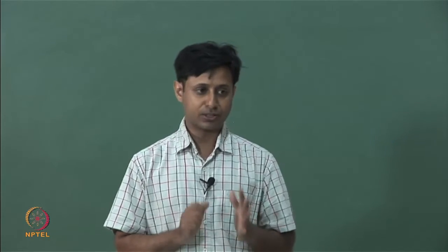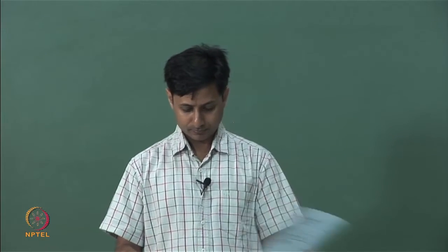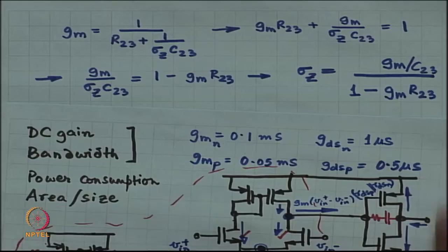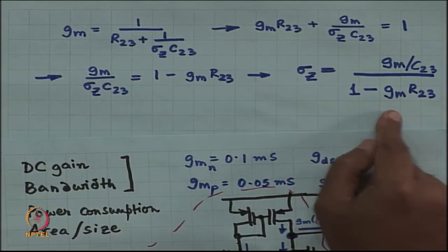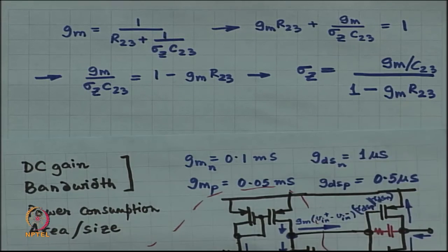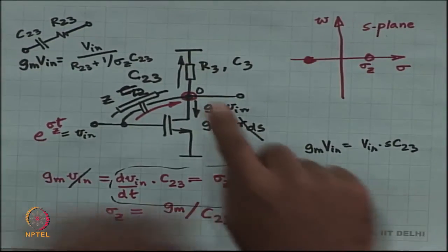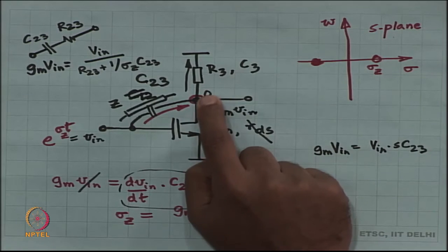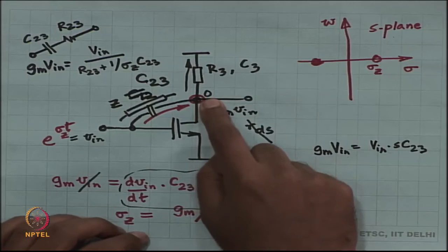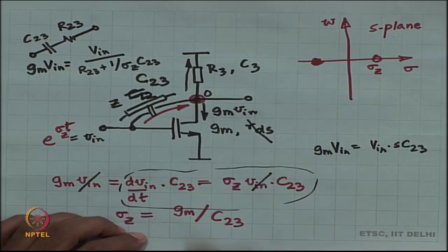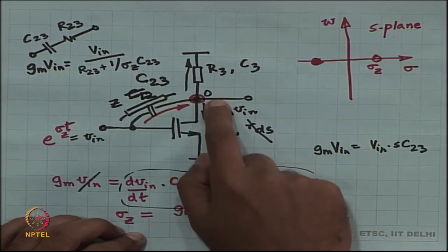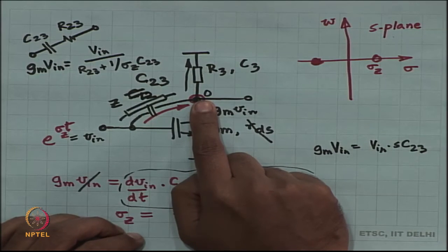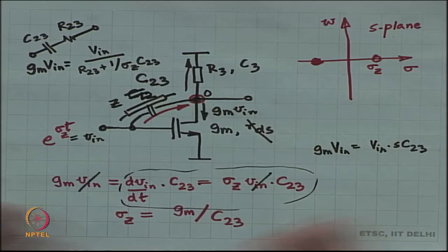Fine. So, what all have we learnt? We figured out how to find out the 0 frequency in a short way, right. What is the short technique? The short technique is to assume that at that 0 frequency the output voltage is equal to 0 by definition. Okay. Then all of these extra things go away, all that remains is G m and whatever is happening in the cross path, right, and from that you can work out the 0 frequency. Fine. This is one thing.